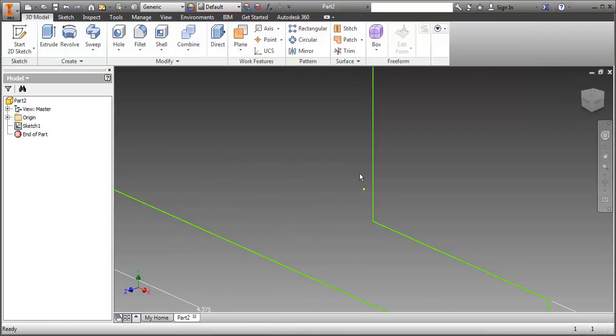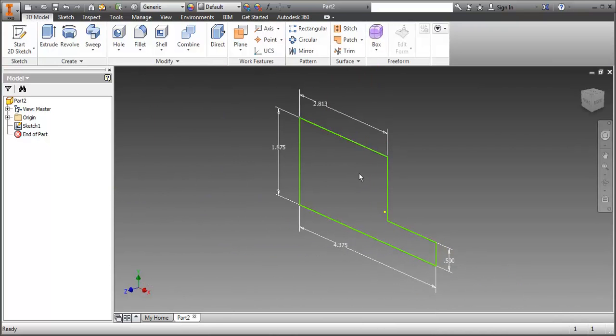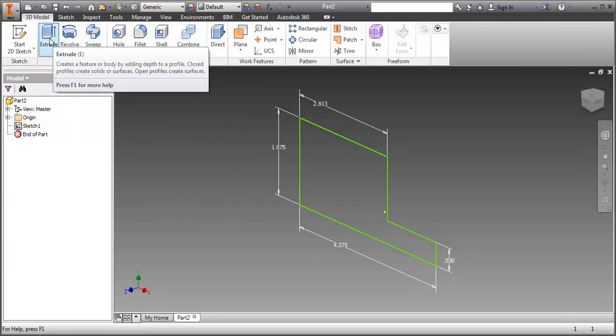All right. Notice it zooms big. So how do you get back? Well, I just double click on the mouse ball, and it does a zoom extents. After you're done creating your sketch and finishing your sketch, you go back to your feature ribbon. All right. And the one we're going to use is called Extrude.